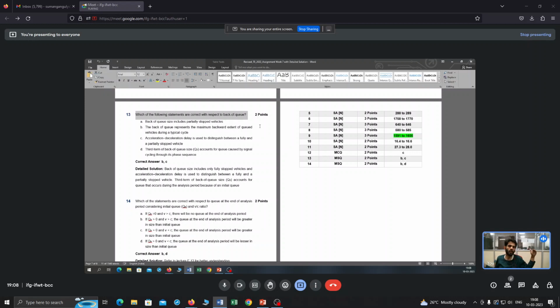It's like a vehicle coming when it is already red. When it is near, it will maybe slow down slightly or stop, and then it immediately leaves, because there is already a yellow and then green, right? So those kinds of vehicles we won't count in the queue. Queue means it is fully stopped. That's why it is queuing, right? But at that transition period, whichever vehicles are actually going through, we won't consider those vehicles, right?